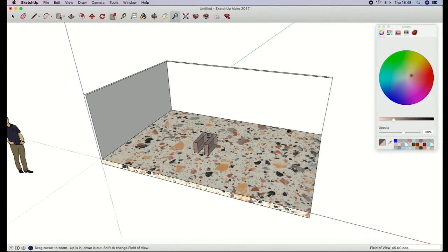So to create a rectangular tabletop, I'm just going to create another rectangle along the shape. So using the line tool, just draw until it's parallel, or even if I just do two lines until they're parallel and then do that. I can also copy that to the other side, so click on the surface, Command C and Command V. Sometimes I place the objects just in space so I can get a better move point on it. So I click to move and then select the endpoint that I want to line up with the other object. So I can drag it to there.